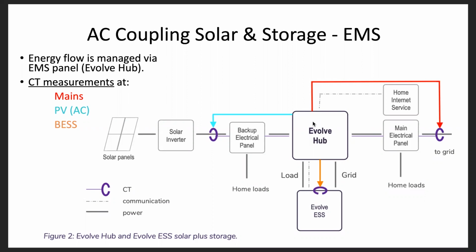So as far as charging the batteries from a generator, it's not designed to do that. And so as far as on the schematic where it would fit in, you would have to have an ATS between the hub interconnection to the service panel and that generator itself. The battery would have to be isolated from the generator if you wanted to serve loads from a fuel type generator.